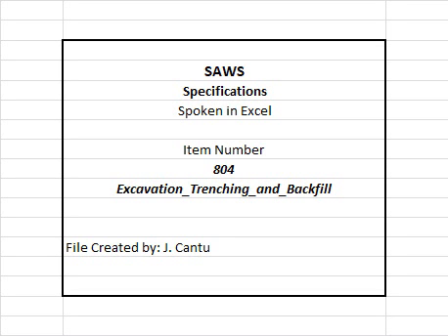1. The contractor will also be required at no cost to SAWS to provide 2 additional tests at the replaced location where the initial test failed and at one location point, randomly selected or as indicated by the SAWS inspector/test administrator. F. Sanitary sewer laterals will be subject to compaction tests at the discretion of the SAWS inspector/test administrator within 100 linear foot segments.